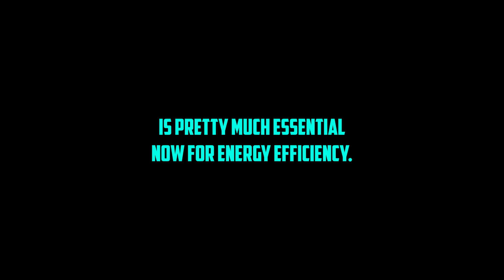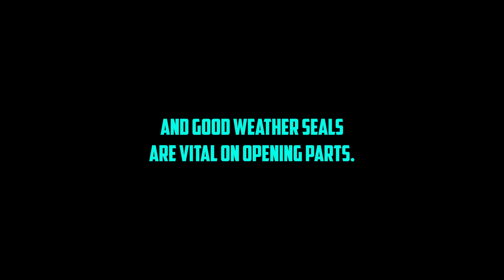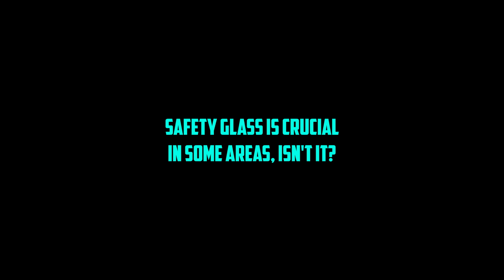Double glazing is pretty much essential now. For energy efficiency, yes. 2 panes with a sealed gap, air or argon gas, 6 to 20 millimeter typically. Cuts heat loss, cuts noise. Metal frames need a thermal break to stop heat conducting through the frame itself. And good weather seals are vital on opening parts. Low emissivity, or low E, glass has a special coating that lets sun heat in but reflects room heat back inside. Safety glass is crucial in some areas, isn't it?